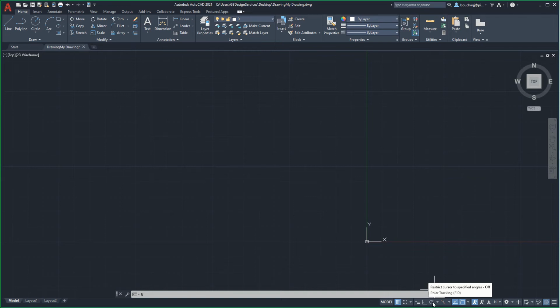The next icon to the right is Isometric Drafting. The pull-down menu allows the user to specify the drawing or drafting plane relevant to the orientation the isometric geometry is required to be placed. Unless the user's drawing task requires these limits, this tool also is best left inactive until needed.